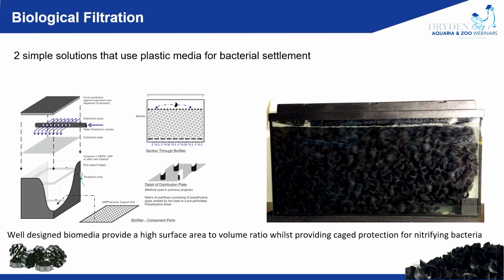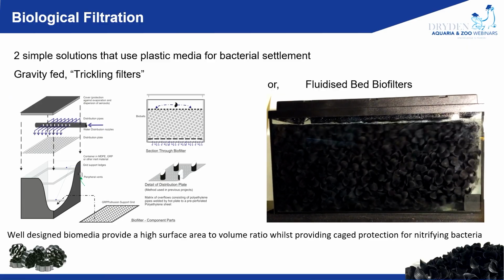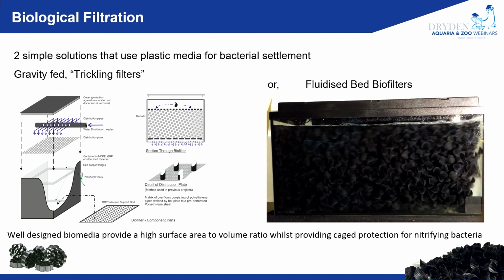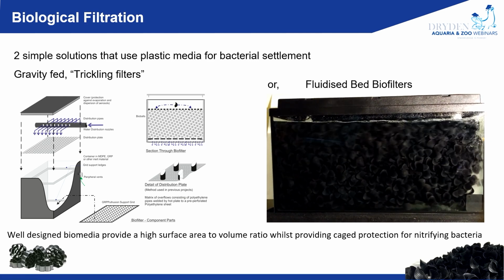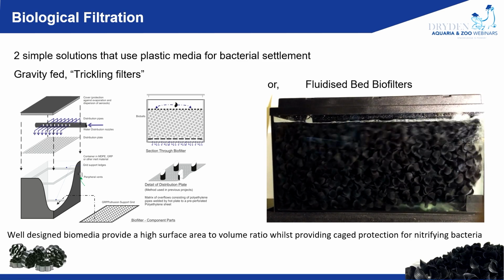These are purpose-built, designed biological filters that are designed for efficient nitrification. It's not a media trap converting particles into ammonia before it's converted into nitrites and nitrates. It is really focusing on the reduction of ammonia through the nitrification process. So it's far more efficient and consistent with regards to nitrification than any sand filter could ever be, because a sand filter is uncontrollable in terms of this process of nitrification.